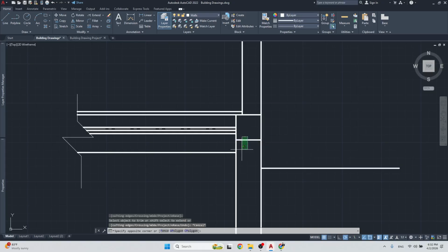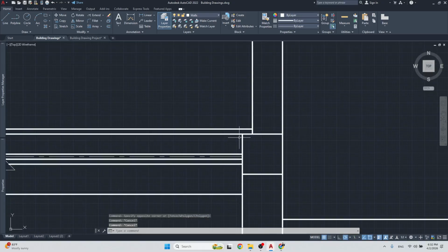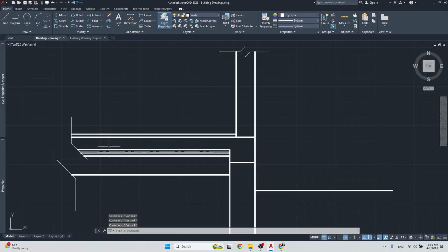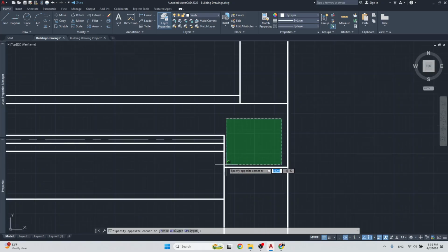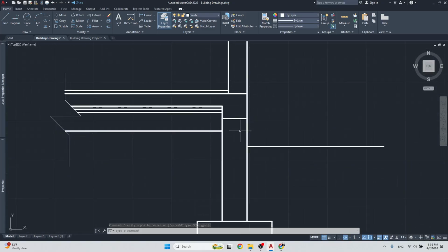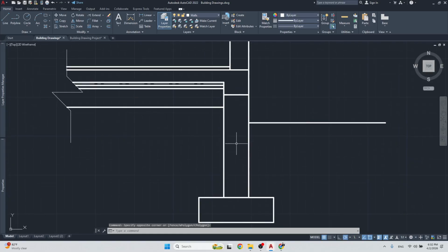wanted this part. Alright, so now I'm going to trim away this one, because this part right here is the concrete floor slab, and the concrete floor slab doesn't just run across the top, it goes down also, alright, to here. So all here is the concrete slab filling down into here, and it sits on top of the foundation wall like so, right, the 8-inch block foundation wall.